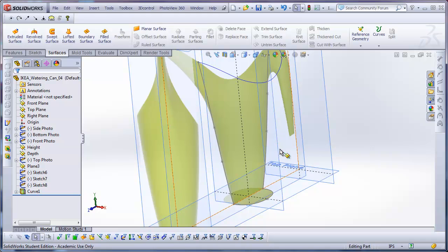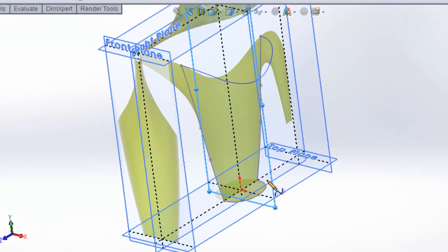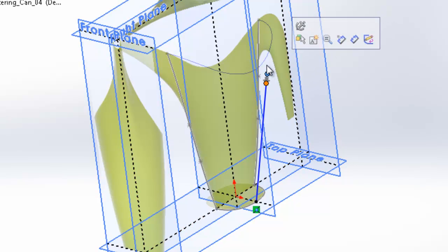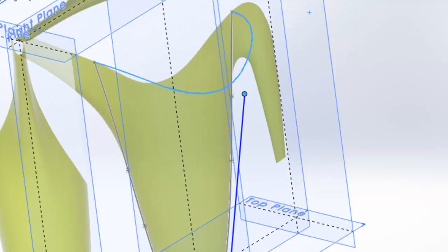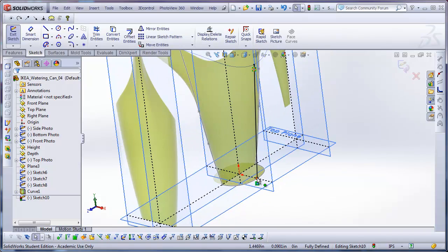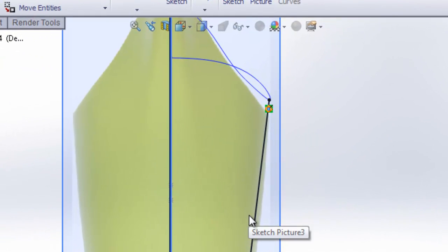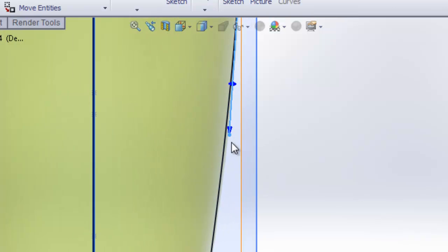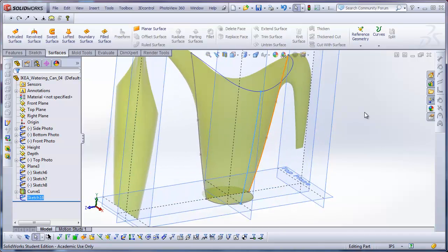I needed a third profile. So on plane number 3, I'm going to sketch, and I'm going to make another spline. Escape to exit out of the spline creation. I'll click on the projected curve and this endpoint, holding the Control button down so I can pierce them. I'll pierce this down here as well. And from a front view, I'll try to match this shape. So I'll just move this arm out to match the curvature. Okay, great. Now I have the curves necessary.